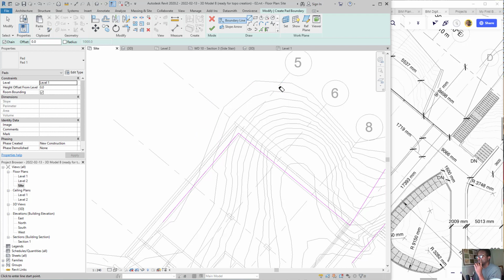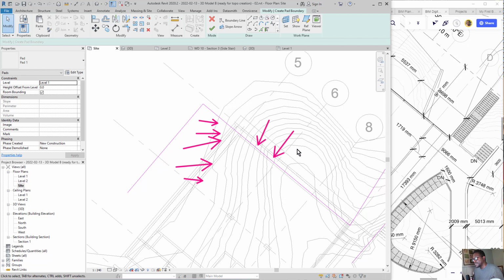As a matter of fact, we're going to need this excavation line that's here to actually come out to this section here, because we want to actually be excavating all of this earth that's going to be here. So I might follow the building line here, obviously, because we don't want to have earth going in the building, but we do need to excavate straight out so that we don't have any earth going inside of this area right here.